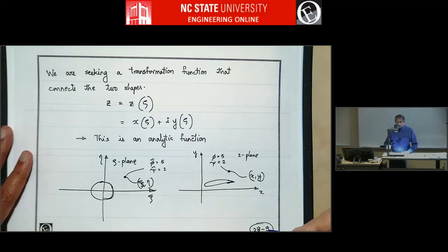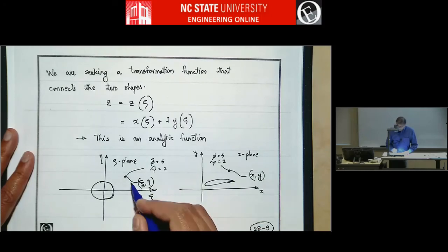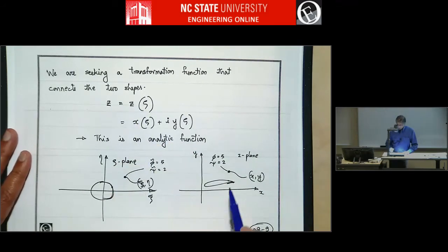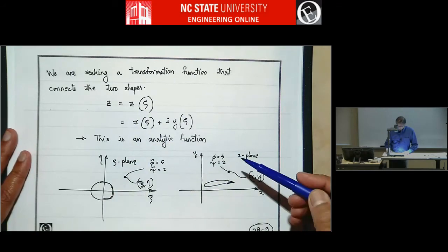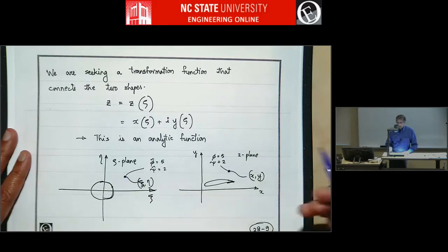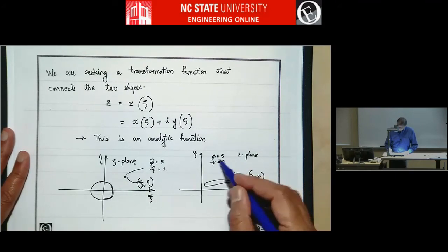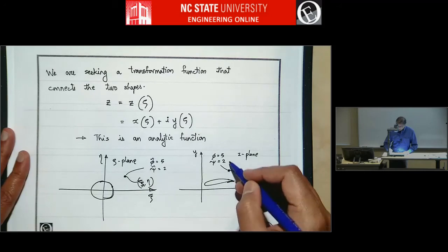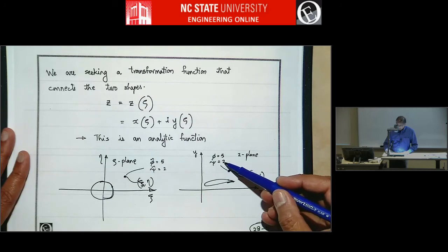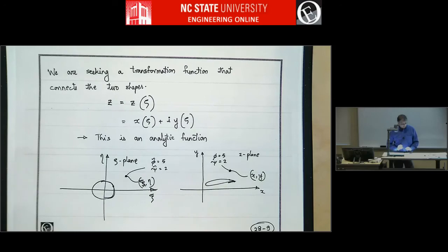If we do this transformation correctly, and let's say this circle becomes some airfoil shape here, this point will get mapped to this point, right, due to this function. Then the value of the velocity potential and stream function will be exactly the same as this. So phi, which is the velocity potential of this flow at this point, will be 5, just like this value, and psi will be 2, just like this psi tilde is 2 at this point.